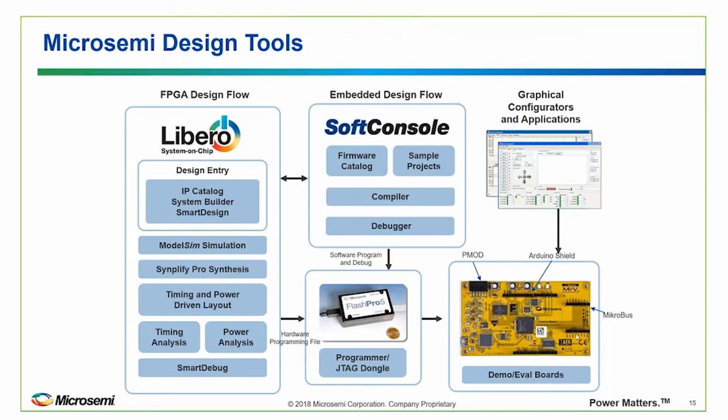SoftConsole is a free firmware development tool that uses the Eclipse IDE and the OpenOCD debugger, and it allows you to create a project, use another tool called the Firmware Catalog that you can download for free from Microsemi, to generate drivers for your peripherals, generate your RISC-V HAL. You can even generate sample projects. Then you can compile, build your application, and then we can debug through the JTAG interface using that same programmer that we use to program the board, and you can develop your application. So I'm going to show you a little demo of that as we go along in just a little bit.